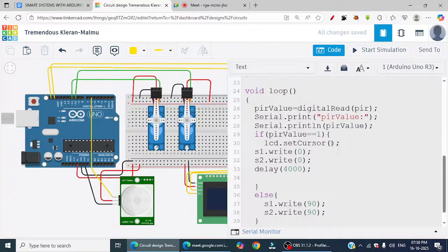I need to select the second row and first column. First number you put is for the column, so the first column will be 0. And I need to select the second row; the second row number will be 1. So I do set cursor 1.